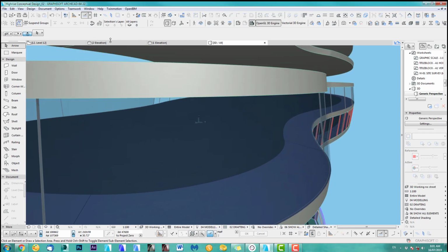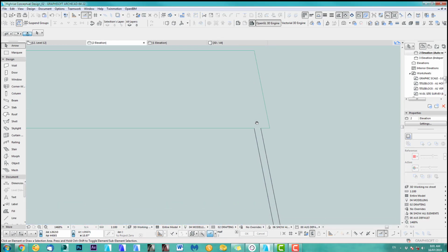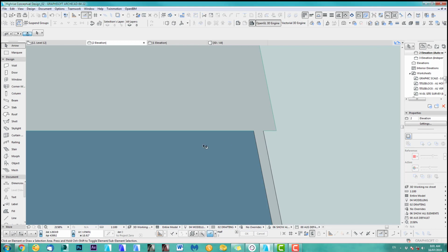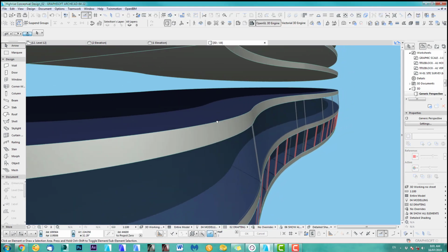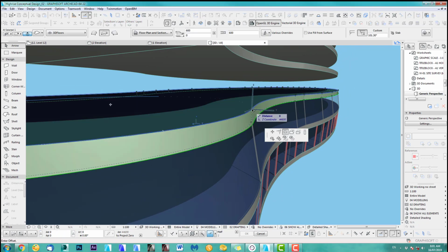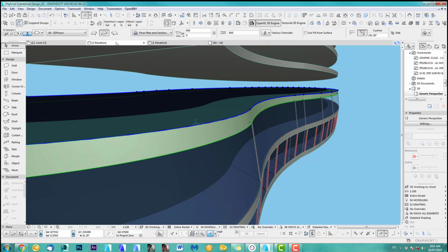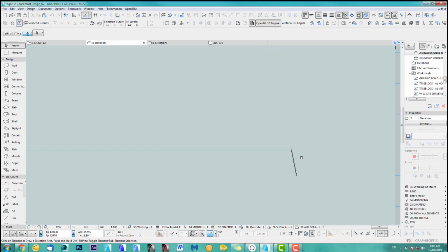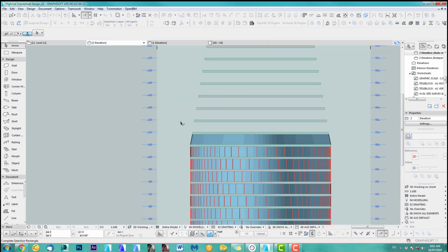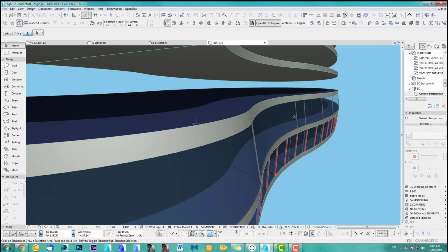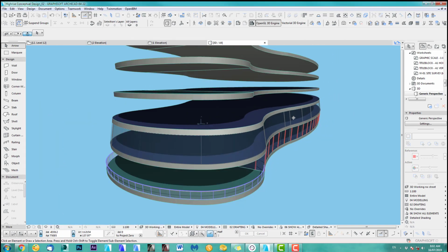Now watch this, you go to the elevation and it will overlap a little bit. Now let's move to there. So what you have to do is measure there to there. It's 69. Okay, so we go back into our 3D and you select this and you just reduce this by 69. Back to our elevation. Perfect. Okay, so in 3D this looks now really nicely closed off, as you can see everywhere.